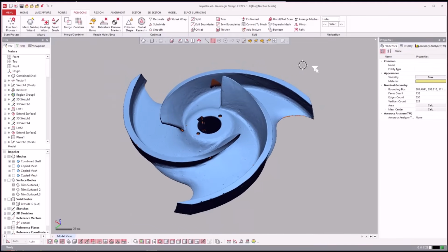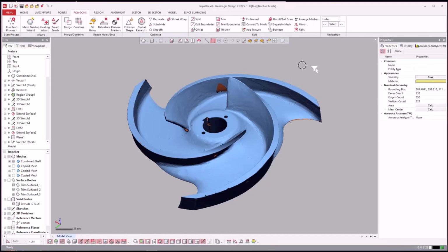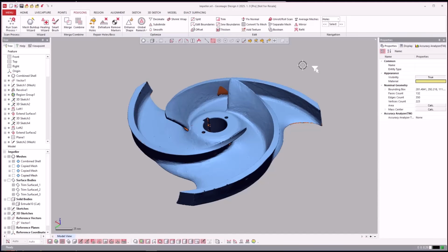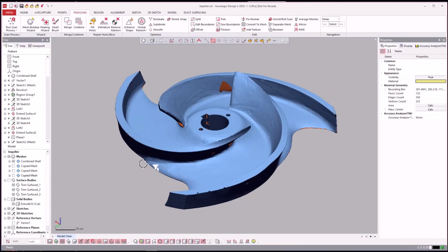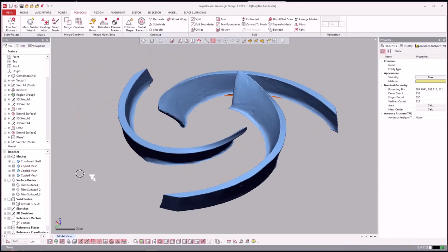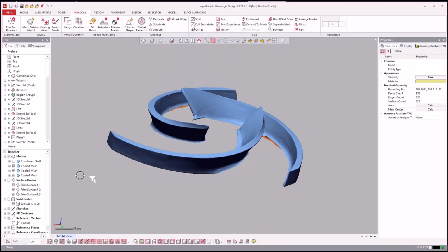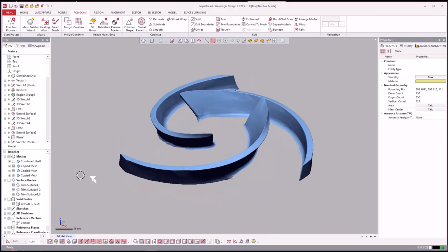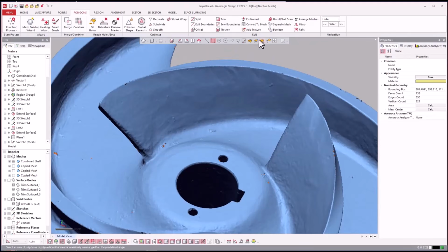So we have talked about this in the past, but this is one of those pieces of functionality that's very powerful, people love, and we just want to highlight it again and how to go about averaging these blades together. So what I have done is I've taken a minute to cut apart and take just those blades and section them out to then use our average meshes tool.